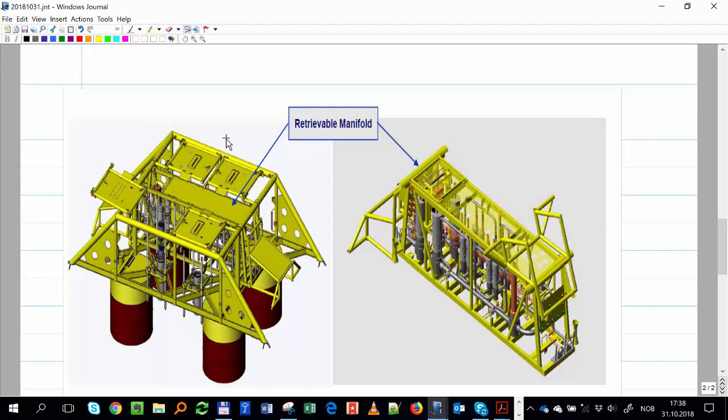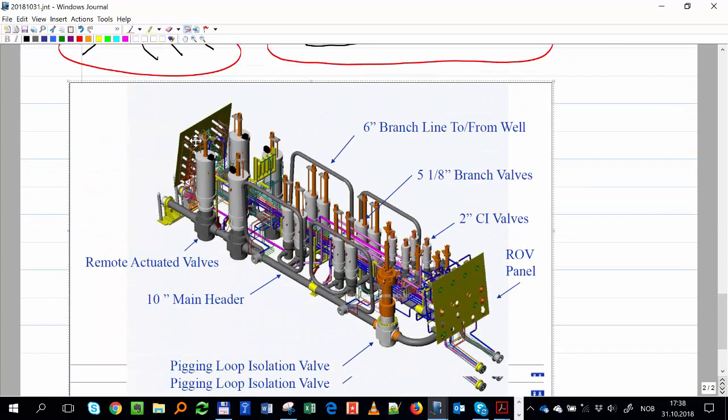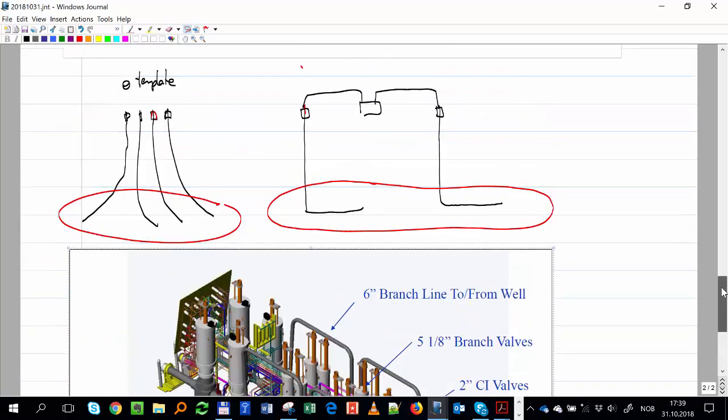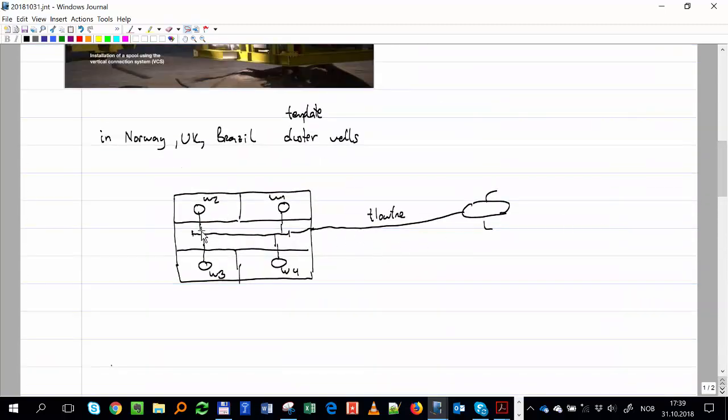Oh. Okay? So, yeah, here you have some help. Okay, so where do we have the connection to the main line, to the main pipeline that will go to the FPSO? Do you see it or not? It's here, okay? It's this pipe here. So if you continue upstream, that's where you should have the header, right? Because in all of our drawings, we are making the header just upstream of the flow line.